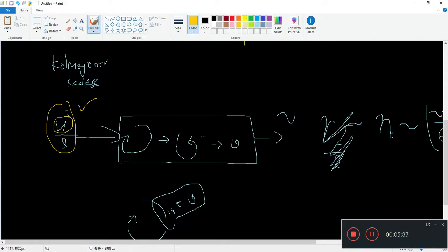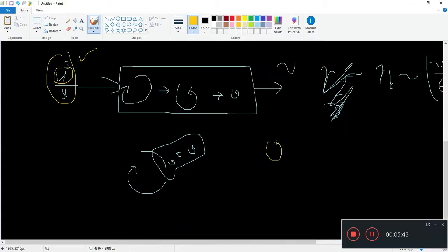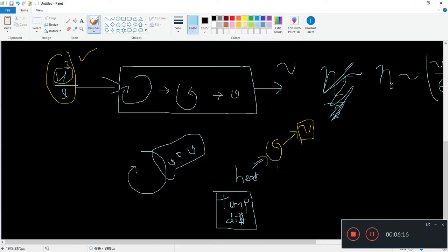So as you do this, how are the eddies dissipated at the smaller scales? Well, if you have the smallest eddy here, you have viscous dissipation, that is one. However, you know what actually drives these eddies, right? What actually gives energy to these eddies? That is basically heat. Heat actually drives natural convection, and therefore temperature differences are the main driving force for these eddies.